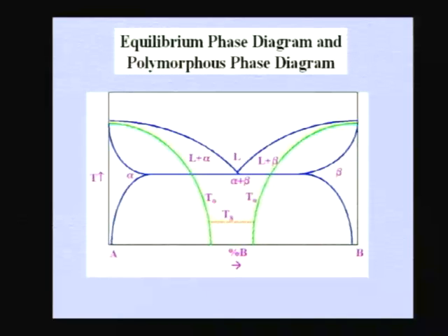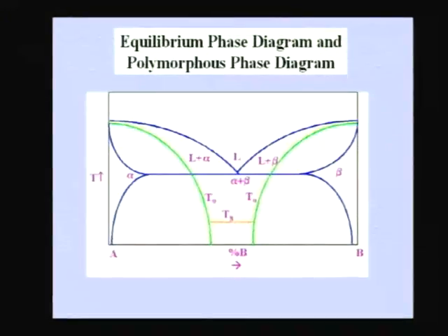If you choose any composition and cool it to such a temperature that the temperature is below the T naught curve for that alloy composition, you will see that particular alloy can transform to the solid having the same composition, which is what we call partitionless solidification. But if the temperature and composition coordinates are above that curve, then the liquid cannot transform to the solid, basically because there is no driving force for the liquid to transform to the solid.